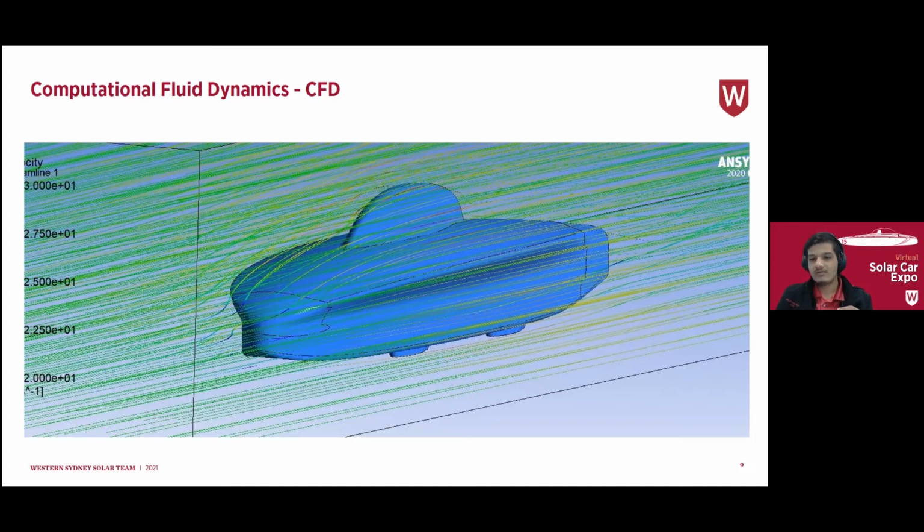In this, we start off with the CAD model of the aerobody that we want to simulate. The main difference to FEA is that instead of importing the aerobody itself, we import all the air around the aerobody and remove the area where the aerobody was. This is because instead of simulating a car moving through the air, CFD actually looks at wind moving over a stationary car at the same speed. The empty area where the aerobody was acts like a wall that the air can't pass through and hence has to go around. And through this, you can see how it behaves.